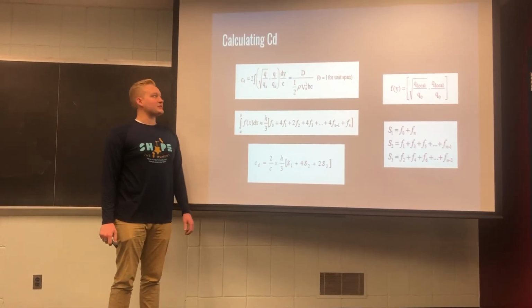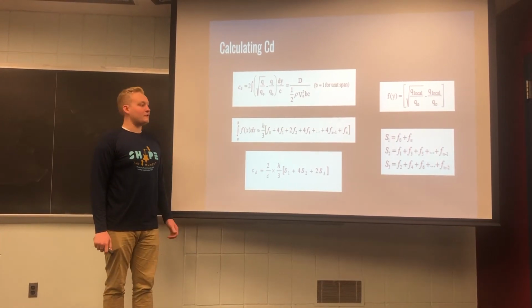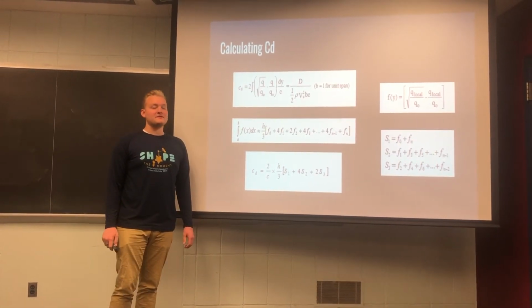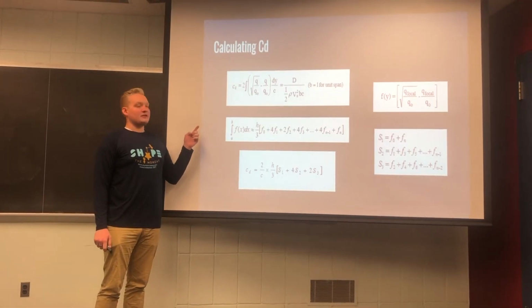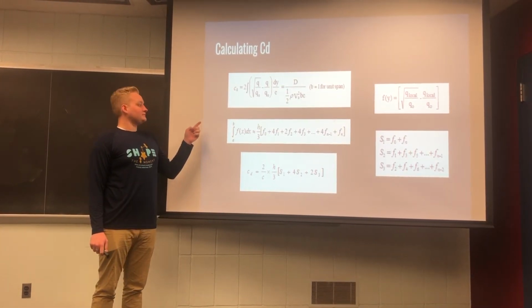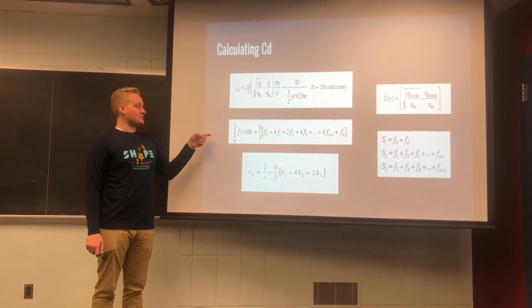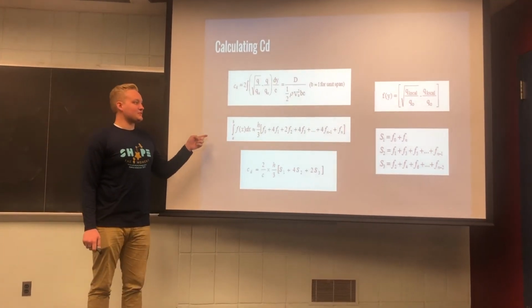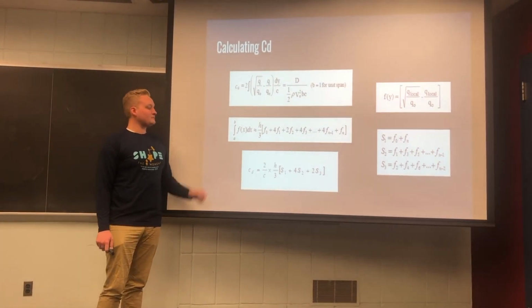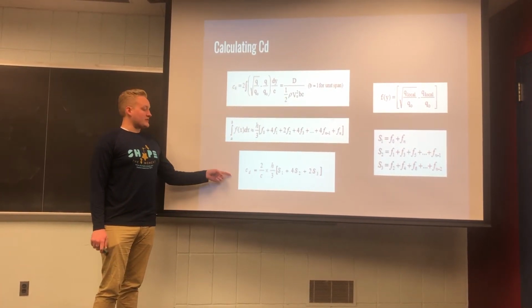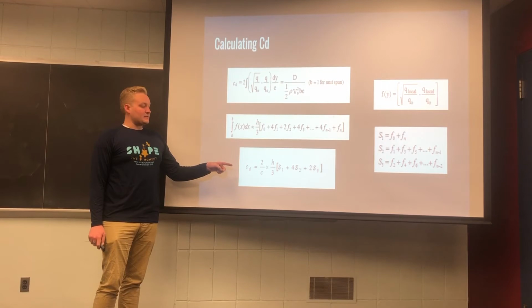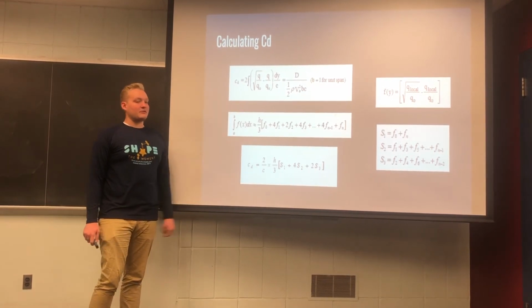My name is Robert Batchelor, and I will be discussing our calculations for the coefficient of drag as well as the corresponding graphs. In order to solve for the coefficient of drag, we needed to solve this complex integral. In order to solve that, we used Simpson's rule. The function that we used for Simpson's rule is displayed on the top right. Once we applied Simpson's rule to the coefficient of drag equation, we came out with this equation, where the S's, S1, S2, and S3 are defined over there.